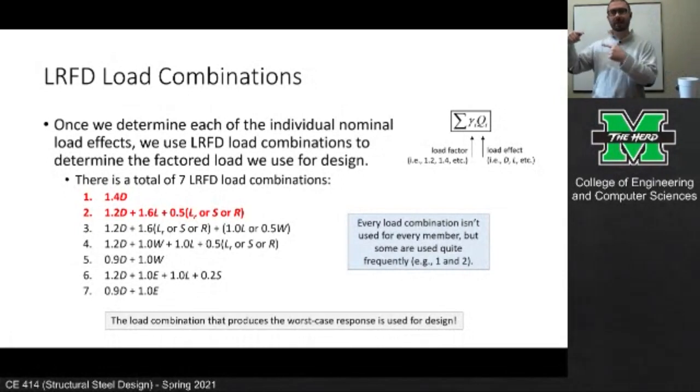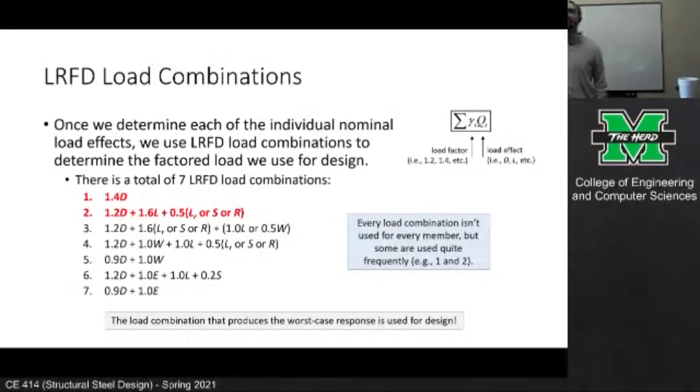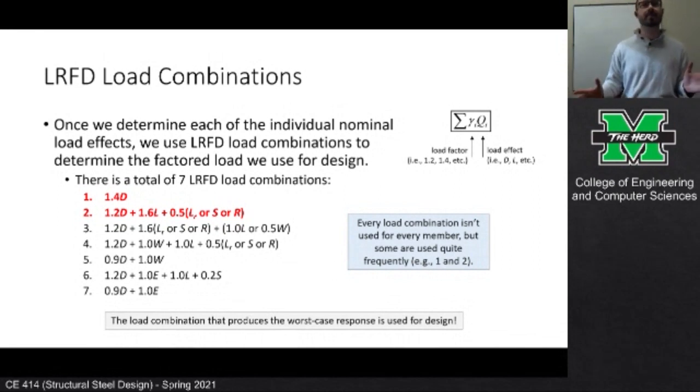So its actual less stable state might be while it's being built. Yeah, it's why you have to use shoring during concrete. You know, you shore up the flooring system, and shoring versus unshored construction is a big thing in structural engineering because shoring can be expensive, and it's a big trade-off.